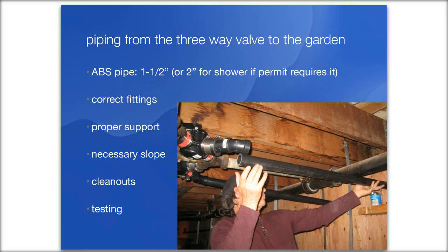You do have code and permitting if you're getting a permit, but if you're just asking about functionality and safety, it's functional and safe to not have a vent and a trap on a greywater drain because there is no sewer gas. But that may be in contradiction to what the code says. So like what Christina said, permit or no permit will determine a lot.